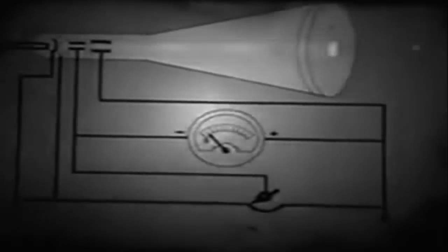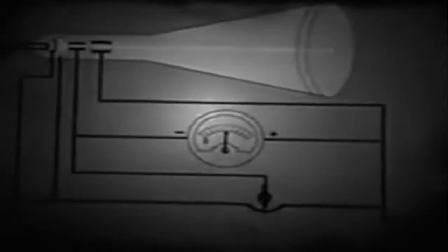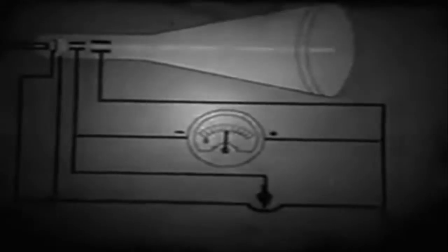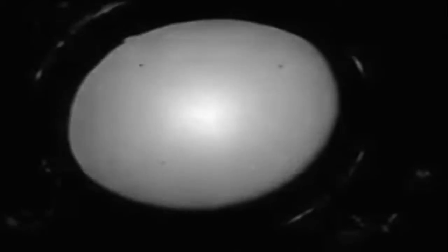It simply controls the voltage ratio between the focusing anode and the accelerating anode, so that the electrons are concentrated in a narrow beam. The proper use of this focusing control enables us to get a sharply defined spot. The position of the spot of light can be controlled by means of circuits associated with the horizontal and vertical deflection plates. In the cathode ray tubes of most oscilloscopes, the electron beam forming the light spot is bent by varying the voltage on the horizontal and vertical deflection plates in the tube.